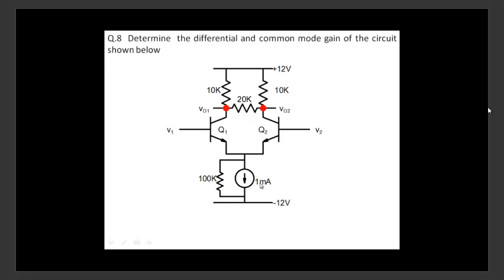So it's not entirely negligible compared to this. So you'll have to add up these two and then say how much current flows here and how much current flows here. It's about 10% of that. Maybe I should have chosen 1000K here. That would have, at least, made the bias point be determined by 1 milliampere here. Anyway, I'm sure you can calculate what the bias points are.